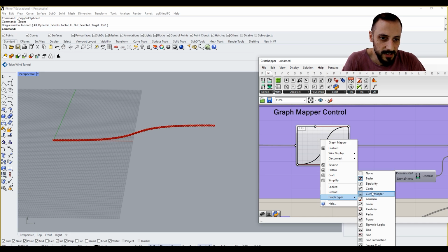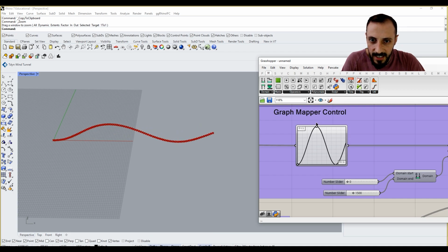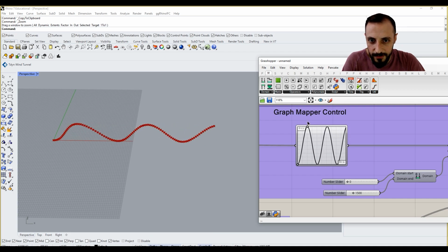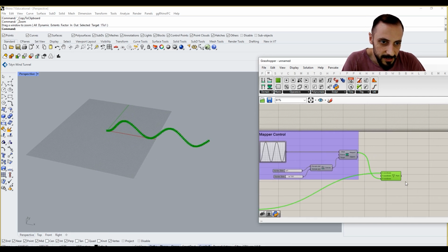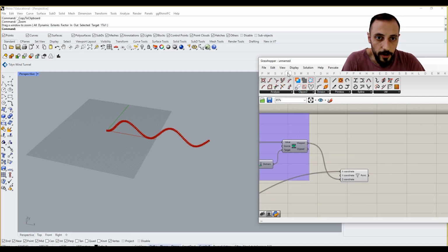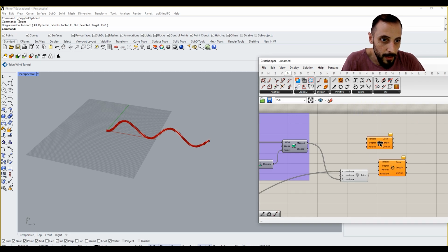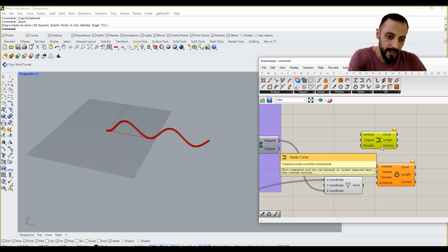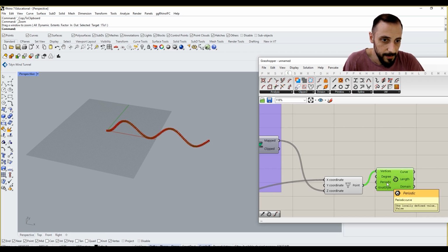And if I right click on this and select, let's say, sine, and if I pull this point in, you see I can create these kinds of curves all over the place. And what I can do here is convert these points into a curve by going under the Curve menu. And under Spline I can say interpolate curve or NURBS curve. Basically, these are the ways that we create curves by using points, very similar to the methods that we see here, like interpolate points, control points through curves, and so on and so forth. So these are our vertices, and it's asking about degree, periodic, knot style.